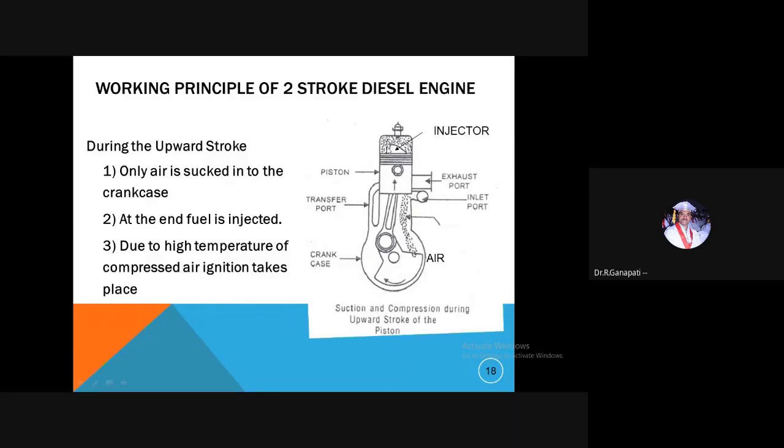And observe here, when the piston moves towards the TDC from the bottom dead center, inside the engine cylinder, in the combustion chamber area, the pressure and temperature rise. At the end of the compression, the fuel will be injected.